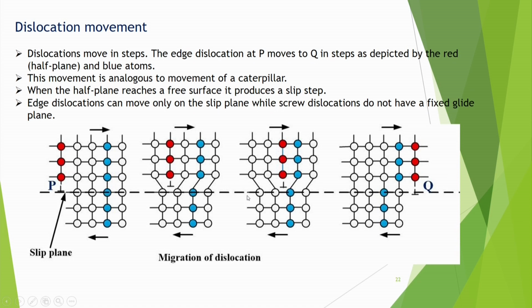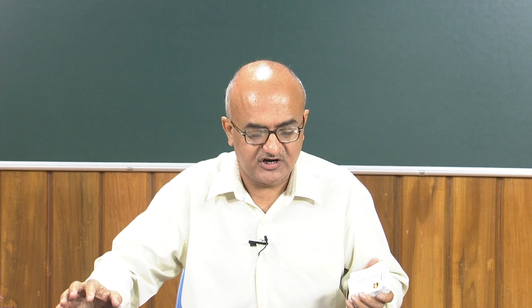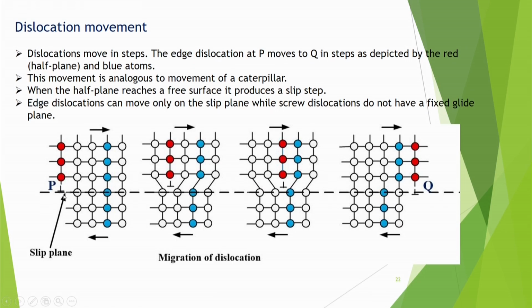Usually there can be two phenomena for plastic deformation. One is slipping. What is slip? Slip means it is due to dislocation movement. Mostly there is a slip plane on which the dislocation will move. Suppose this is the point P, this dislocation, then it migrates to another point. It comes in this direction when force is applied, then a further force application migrates it to this point, and finally it has come to this one. So this type of migration of dislocation is causing this.